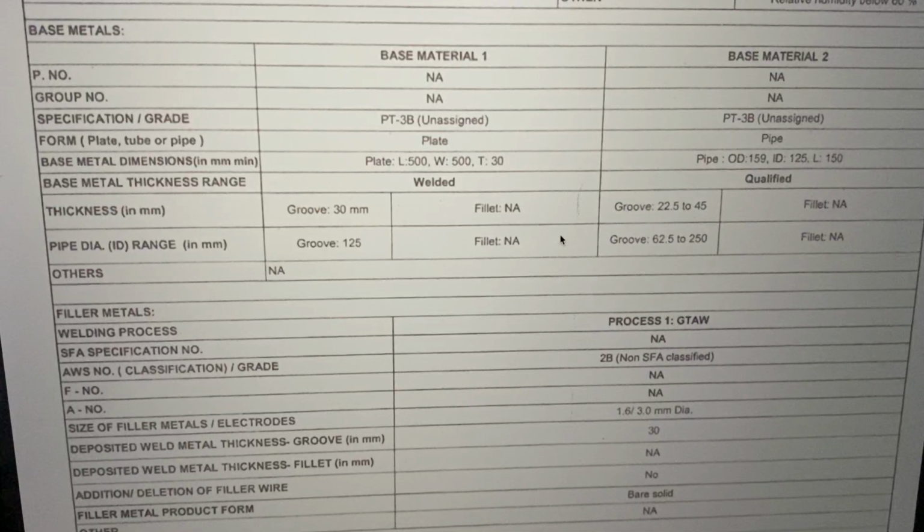Base material dimensions are given here. These are mainly to understand what size of plate we have taken. Thickness is surely to be noted down, but also what kind of mass we have taken, especially when we are talking about highly conductive materials or materials with a very low coefficient of expansion, where the distortion levels and heat accumulation may be completely different. The learning we want to take from this WPS PQR is how the weld is going to behave, not only property wise but also dimensionally and in overall characteristics.